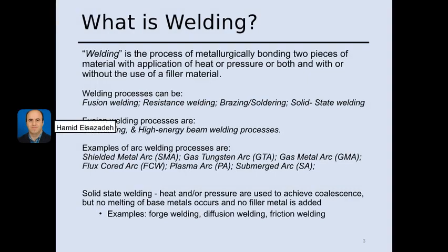What is welding? Welding is a process of metallurgically bonding two pieces of material together with application of heat or pressure, or both of them, heat and pressure. The process can be done with a filler material or without a filler material. And there are many different welding processes.